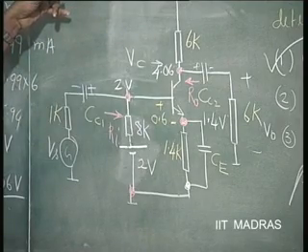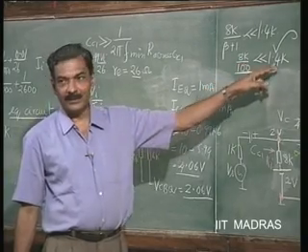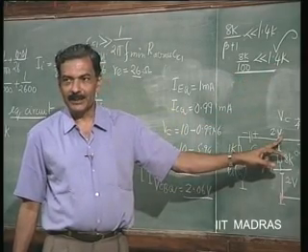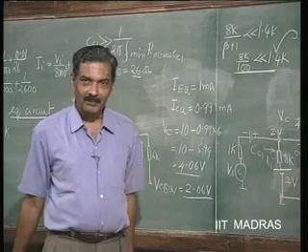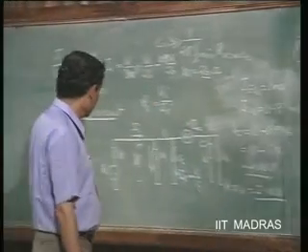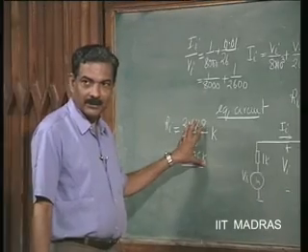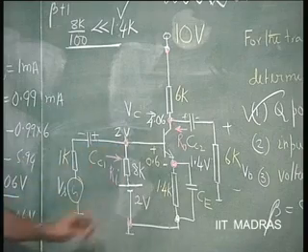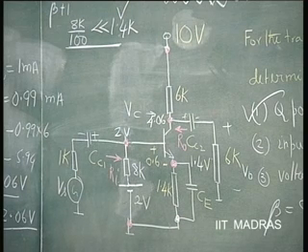If you make it 26 K, it will not satisfy this relationship. So, this will no longer be a stable 2 volts. Okay. So, these are the compromises that are made in the design. Some amount of signal is going to be lost, because this bias resistance is going to take away a certain amount of current. Okay. So, what is now the gain?